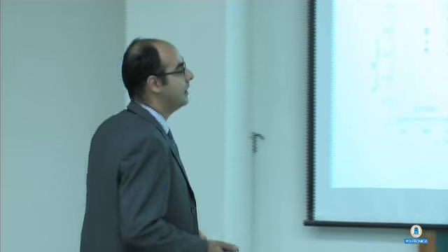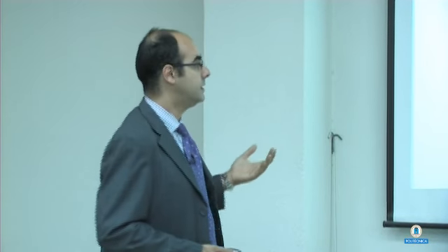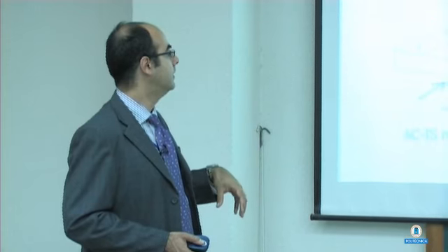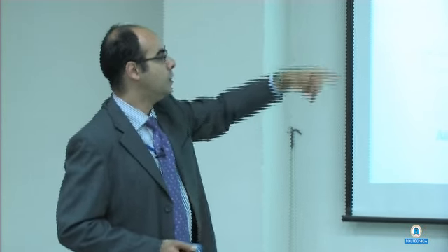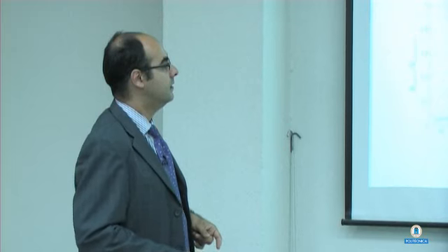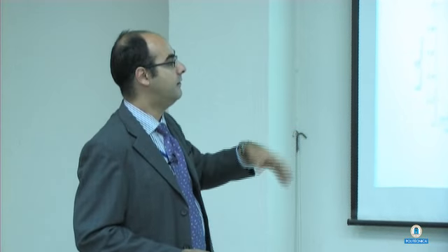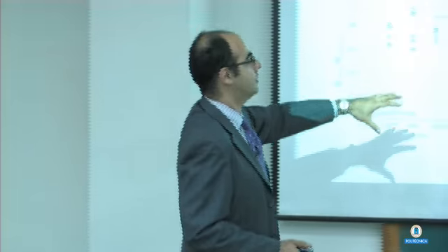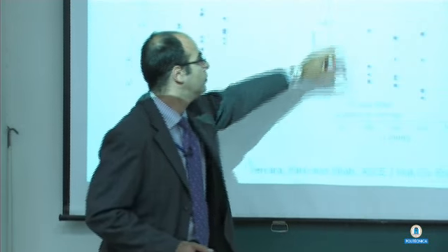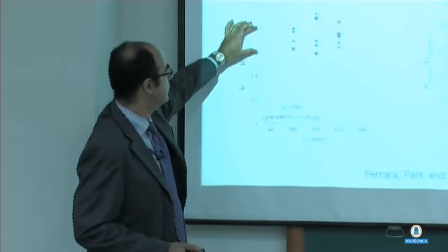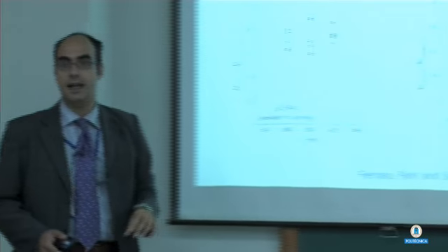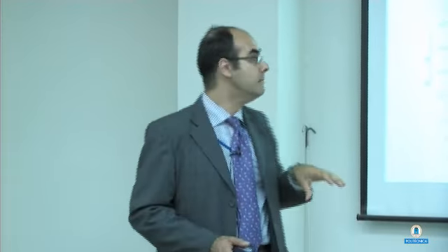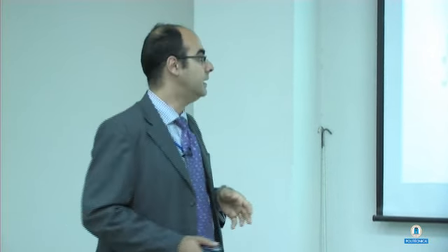On your right, you have the ratio between the resistance of the matrix and the resistance of the composite, which we know is an indicator of the effective content of the fibers in the cells in which we divided the specimen. You can see that with vibrated concrete, we have a very wide dispersion of the results. We range from 1.2 to 1.8, while with self-consolidating concrete, the results are much narrower. So it really means that fibers are homogeneously distributed in the specimen.